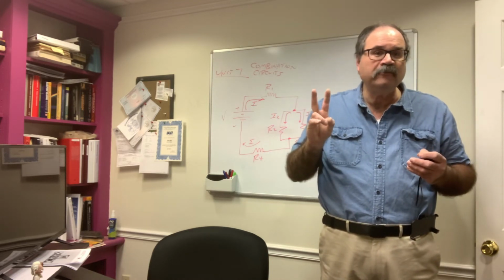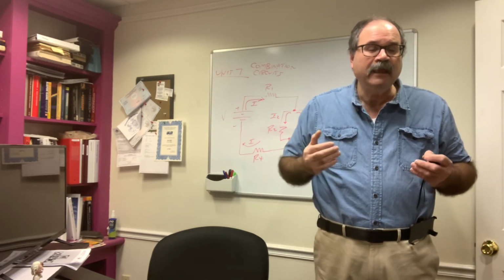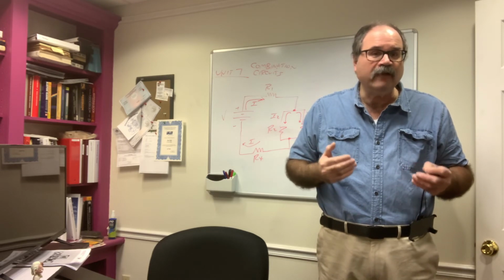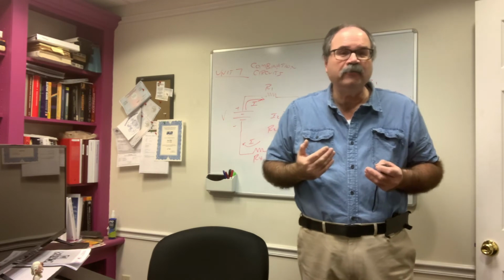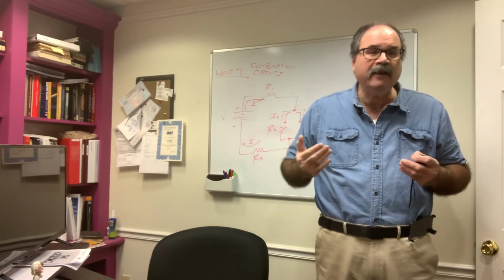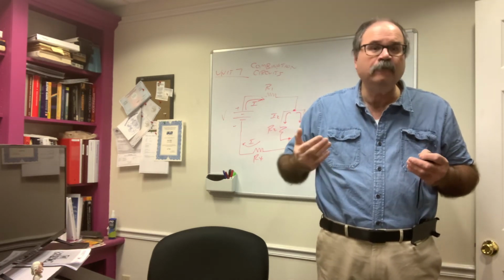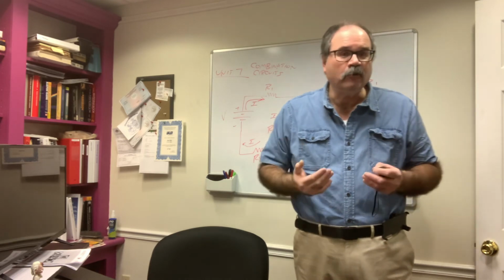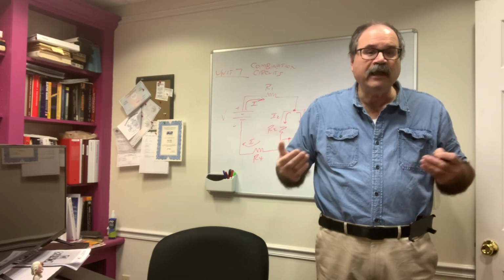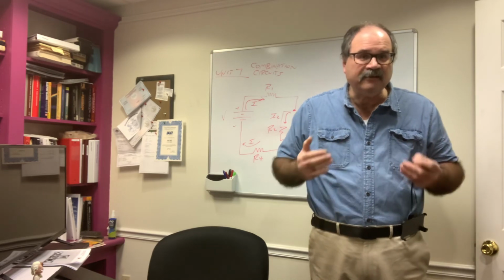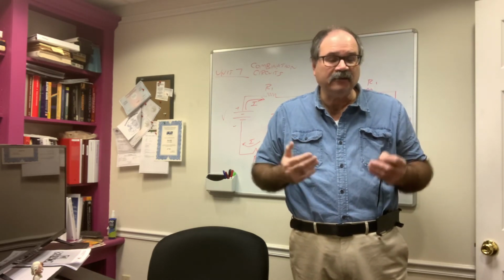Equivalent resistance is a little bit different, with two different algebraic expressions. For only two resistors in parallel, remember, R equivalent is R1 times R2 divided by R1 plus R2. If you have more than two resistors in parallel, it is 1 divided by 1 over R1 plus 1 over R2 plus 1 over R3, for example, if we were to have three resistors. Power supplied and power dissipated work exactly the same as they do in a series circuit.